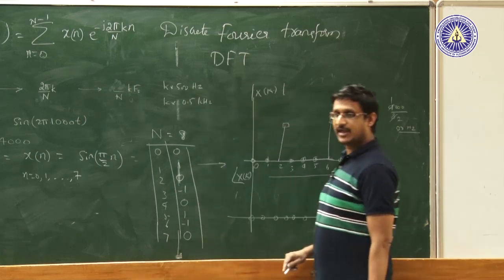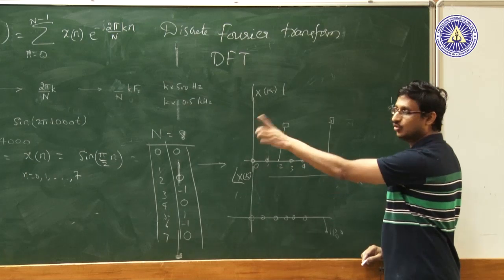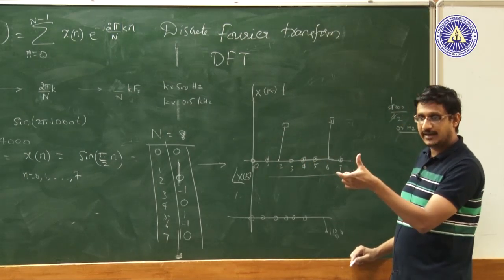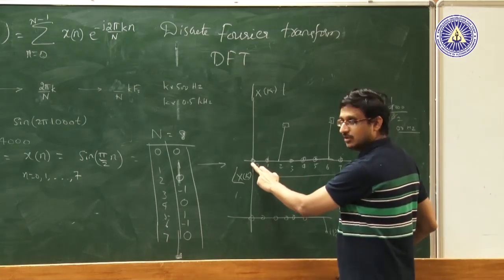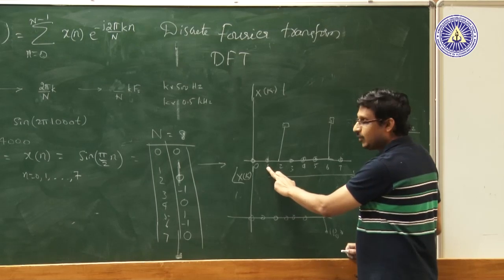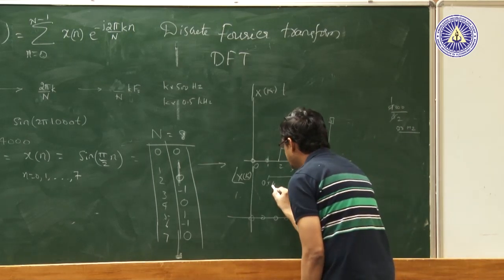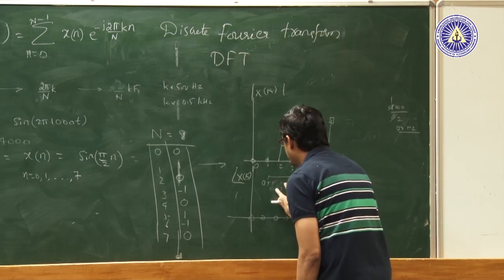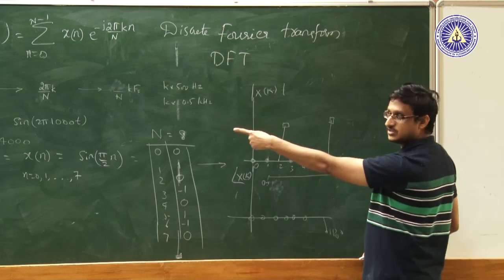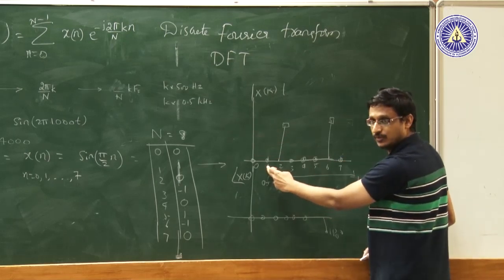Okay. So, k equal to 0 will be 0 kilohertz. So, obviously, this signal has no DC component. The entire sine function is fitting nicely into the time domain, and therefore, the 0 hertz frequency component is 0. This k equal to 1 in fact corresponds to 0.5 kilohertz, right. So, if I write f in terms of kilohertz, this would be 0.5. Clearly, the signal originally is not at 0.5 kilohertz, right. Therefore, that term will also be equal to 0.